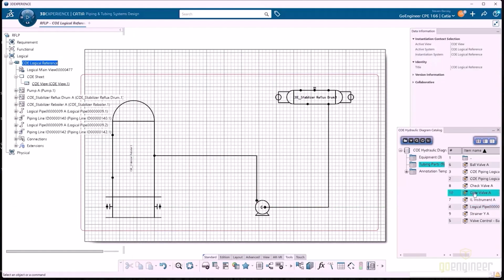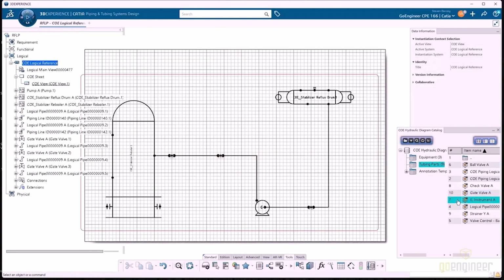And there we go. You can see I've also created some check valves, gate valves, things like that. And so they're real easy. You just drag and drop them on. So drag and drop those. Make sure that the line ID is highlighted in red when you drop it. If it's not, then you missed, and it's not going to automatically break that line ID.